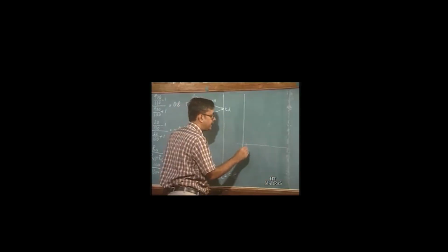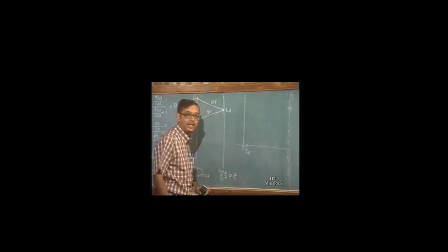If you now observe the waveform at the load end, at Td, which is the delay of the line, the voltage you have is 10 plus 8, which is 18 volts. So the waveform goes all the way up to 18 volts at t equal to Td.